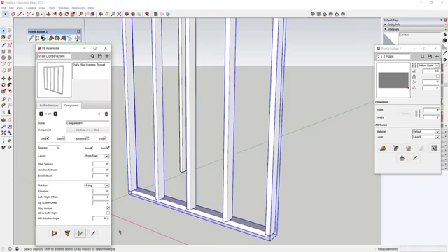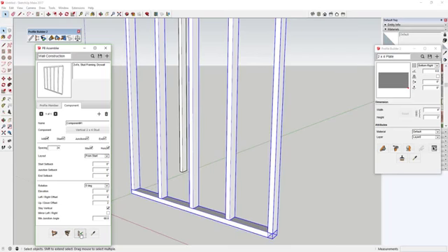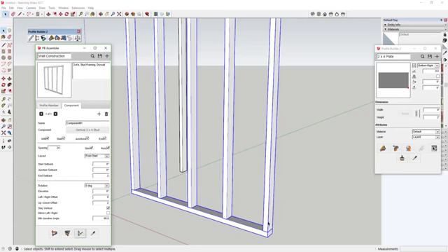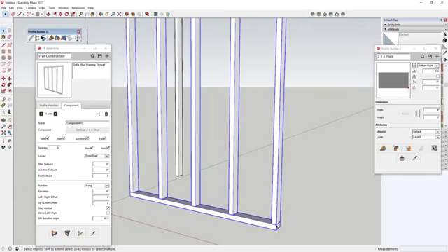Oops, that's not what we want at all. Sorry about that. It's not the left-right offset. It's actually the end setback. So this is basically setting how far set back this object is from the end. So in this case, this is taking this object and putting the corner point on the very end here. What you want to do is you want to set that end setback to 2 inches. And then if you update that, you can see how it tells it, oh, okay, go from 2 inches from the end is where we're going to start our objects.